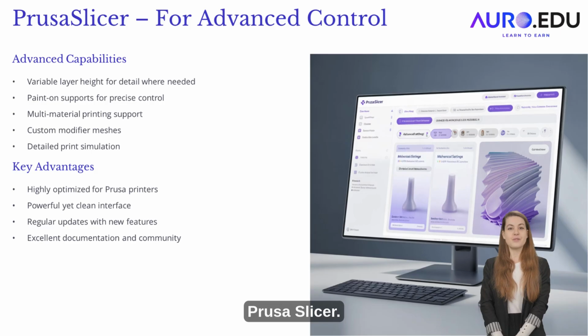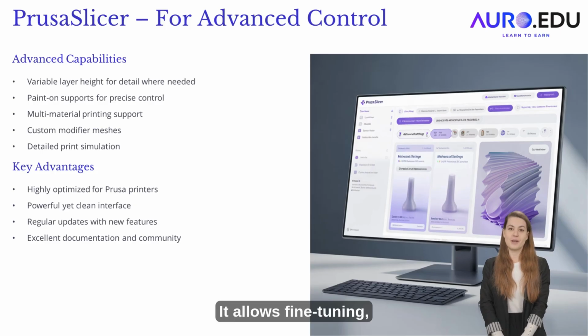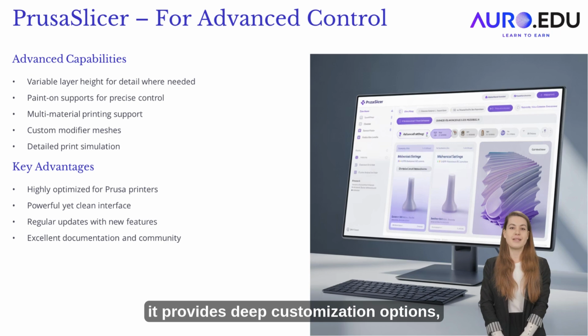8. Prusa Slicer. For advanced control, Prusa Slicer is preferred by experienced users, especially with Prusa printers. It allows fine-tuning, variable layer heights, and multi-material prints. While more complex, it provides deep customization options, helpful for advanced projects.